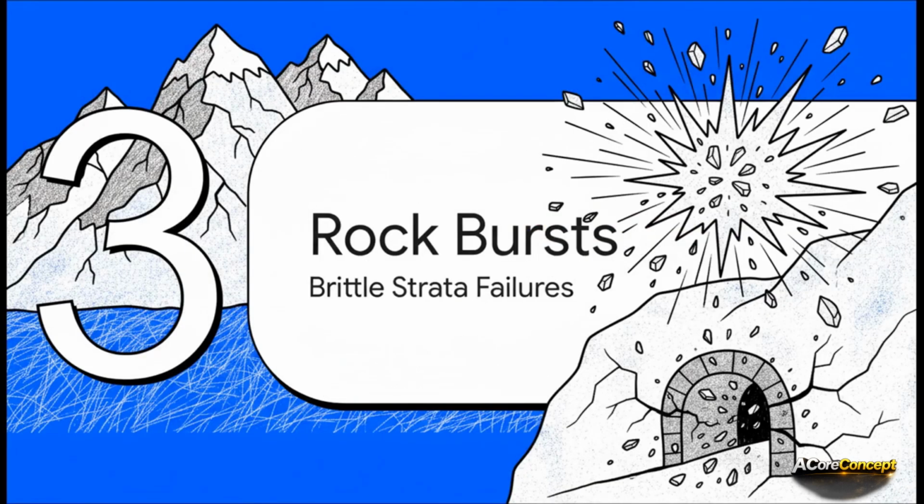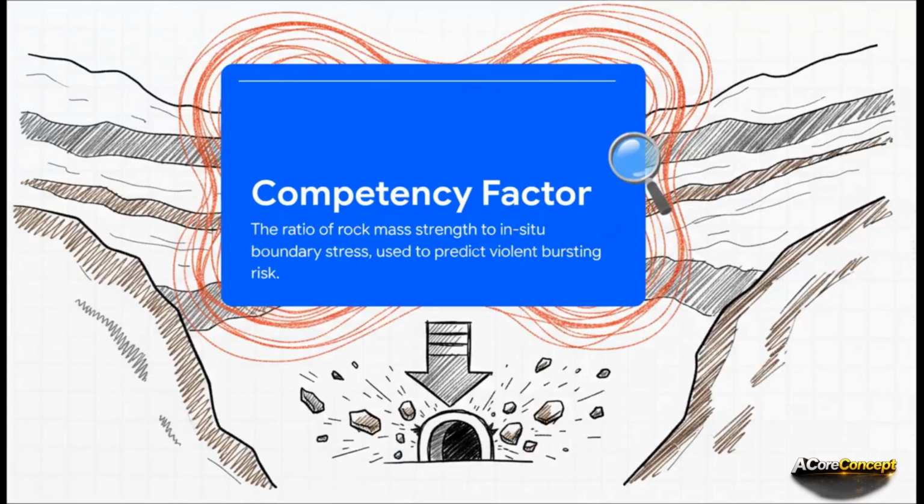Section 3. Rock bursts in brittle strata. As we go deeper into the Higher Himalayas, the rock gets much harder, and the danger shifts from a slow squeeze to a sudden explosion. In these deep, brittle strata, we use the competency factor to predict failure. When you have incredibly high-strength rock sitting under a massive amount of overburden, often way over 1,000 meters, the tangential stresses become astronomical. Under these conditions, the rock doesn't gracefully bend or slowly squeeze.